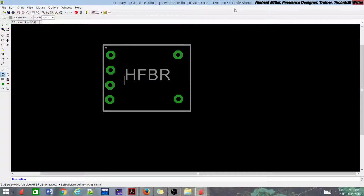Hello, what's up guys? In the last tutorial we had left this particular library file designing incomplete. So let's complete the design. So till now we have completed the package making, which will be used in the routing process, that is the layout process. But we need to also make the schematic out of this particular package, so that that schematic can be used in order to make a circuit in the schematic file.